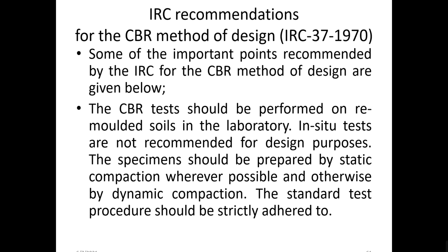Depending upon the number of blows given by the rammer, either 25 or 56, light compaction method or heavy compaction method, it totally depends upon the different weights with which the ram is going to fall upon the soil surface. Either it can be called static compaction or dynamic compaction. The standard test procedure should be strictly adhered to. So what IS 2720 of 1970 indicates is that they are recommending the soils to be tested in the laboratory by either static compaction or dynamic compaction.